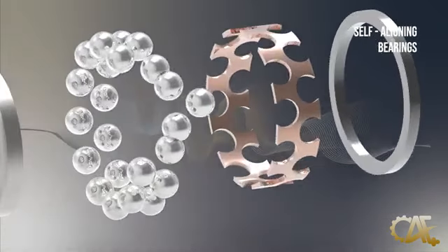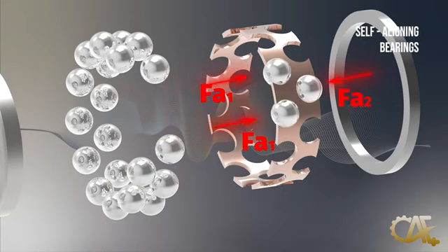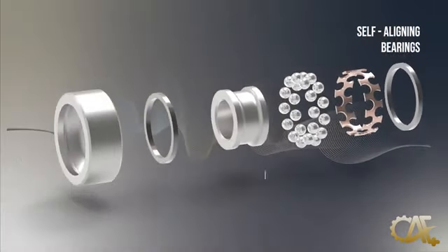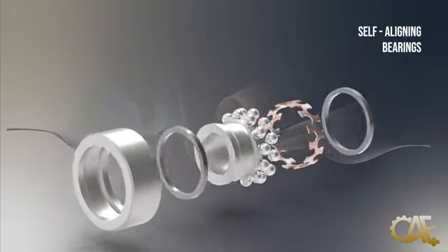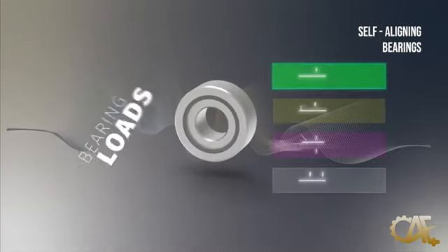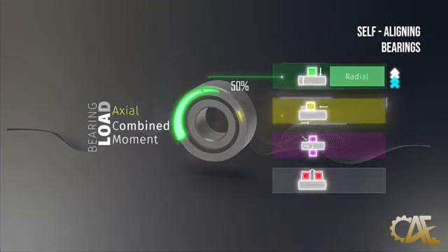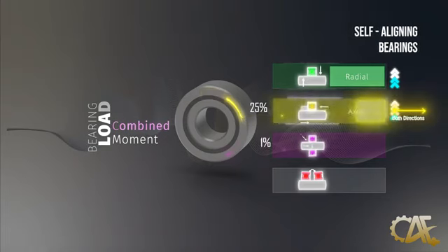In situations of shaft misalignment or mounting errors, traditional bearings might face challenges, risking premature wear or failure. However, the self-aligning bearings with their staggered elements smoothly handle such issues, achieving uniform load distribution and maintaining smooth operation. While these bearings are predominantly designed to address misalignments, their load performance chart indicates a highly possible application scenario for radial loads where they earn 2 points, with their axial load slightly trailing their radial load rating and earning only 1 point. In combined loads, they score similarly.